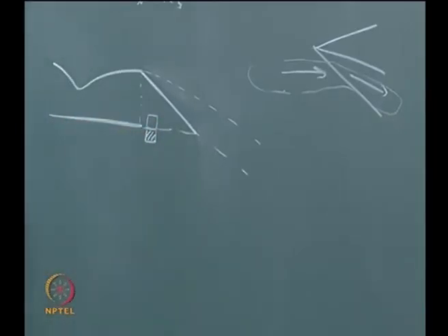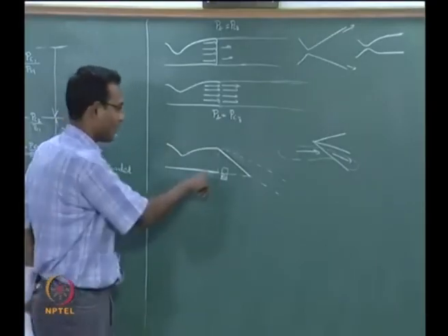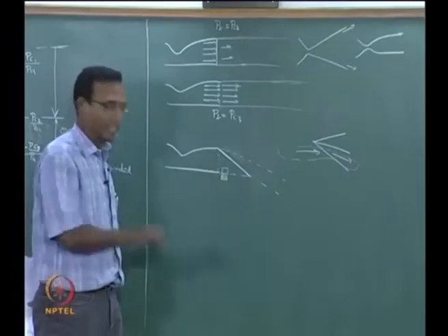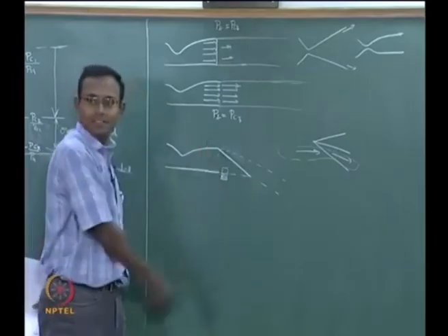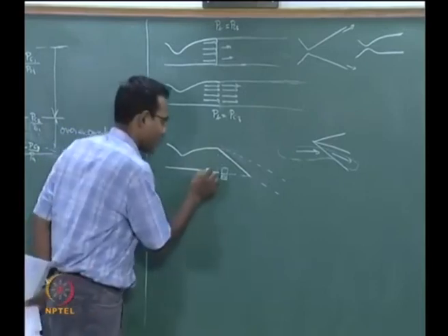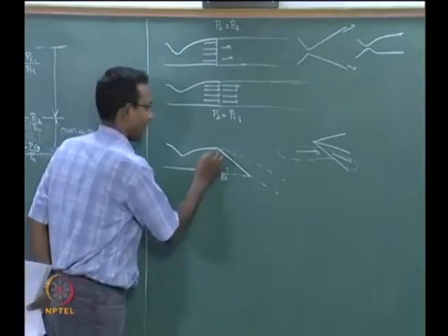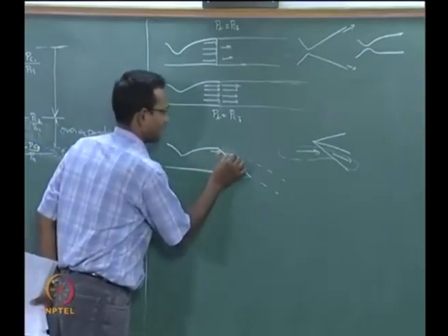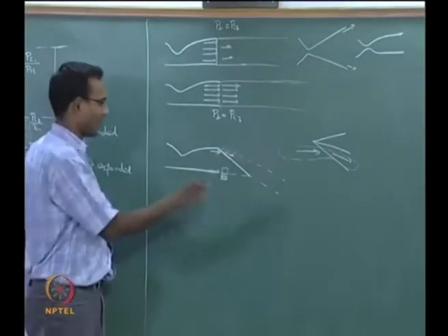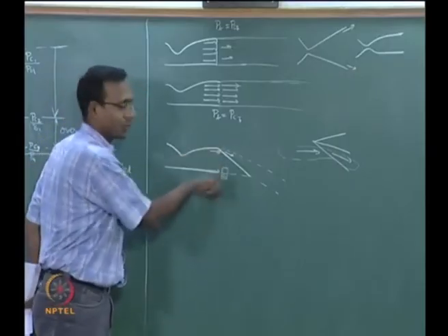What will happen? Naturally this fluid element will push that fluid element up. Along that border there is unequal balance, right? One guy is pushing less, other guy is pushing hard, then the boundary will move. What does that mean? This last fluid streamline is going to turn inward. We said this fluid element turns this way. Why? For the same reason as that side, and so it formed the shock.